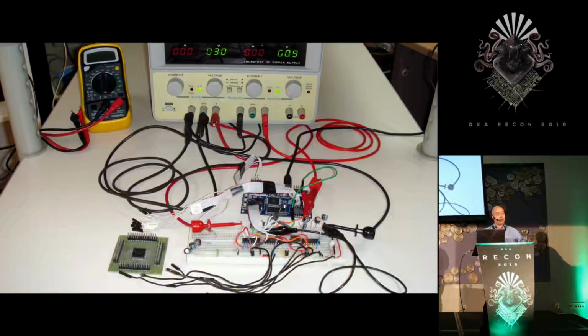So I started to work on a glitcher to study the chip a little bit more in depth. The timing tests I did on the ACP suggested that the 6502 was running from an internal clock source, so this rules out a clock glitch attack. Voltage glitching makes sense, and with the age of this chip, it seemed pretty reasonable to expect it could be susceptible to voltage glitching. The stronger protections are generally more recent.